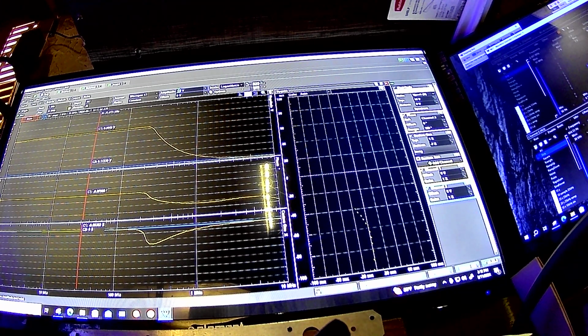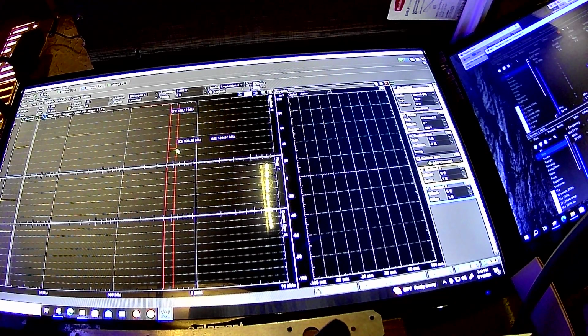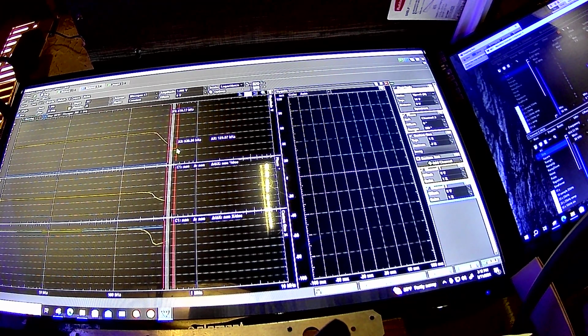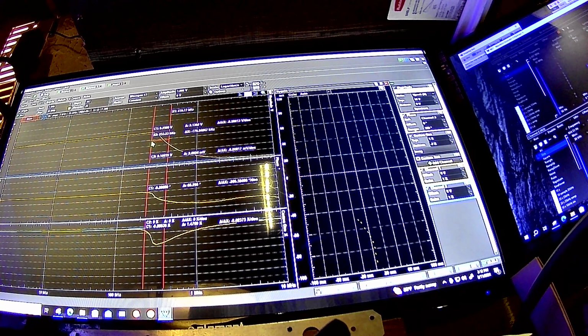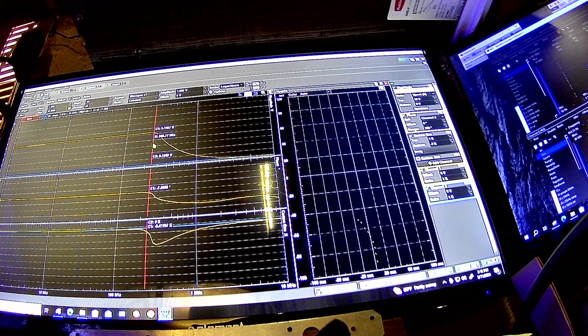That would be for a plus or minus 5 volt output swing, but 6 volts peak to peak. Alright, so that's, god damn it. I hate that. But it's about 240, 250 kilohertz or so that it's given us a power bandwidth on.